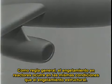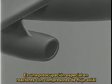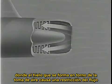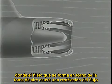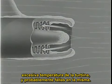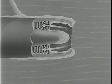As a general rule, jet engine icing occurs under the same conditions as external structural icing. It is of particular concern in turbojet engines of the axial flow compressor type, where the ice forms over the inlet guide vanes, causing a restriction in airflow. The result is reduced engine thrust, excessive turbine temperature, and probable turbine failure.